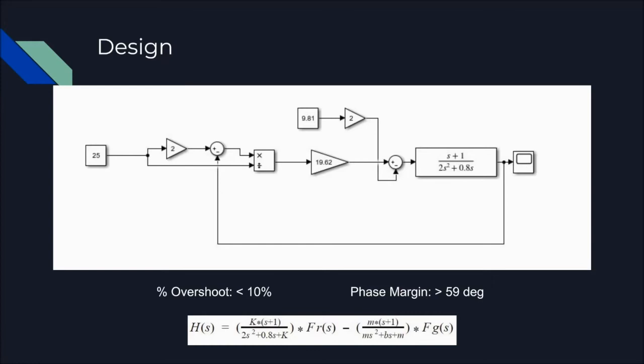During our design, we realized that entering a force and having the feedback return a height was counterintuitive, since these could not relate to each other. To overcome this issue, we implemented an input system that would take a designated height rather than a force. This height would then be implemented into a function that compared the intended height with the current height, resulting in a fraction. This fraction would then be multiplied by the gain. Setting our system up like this allows our force input to be related to the gravitational force.